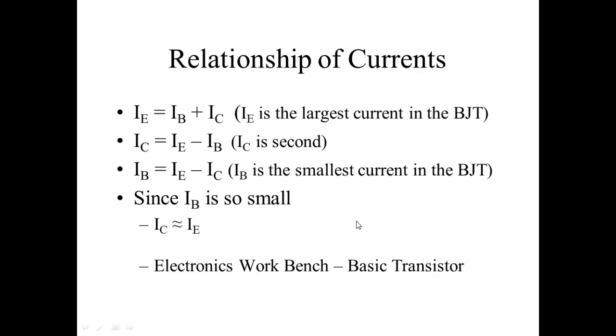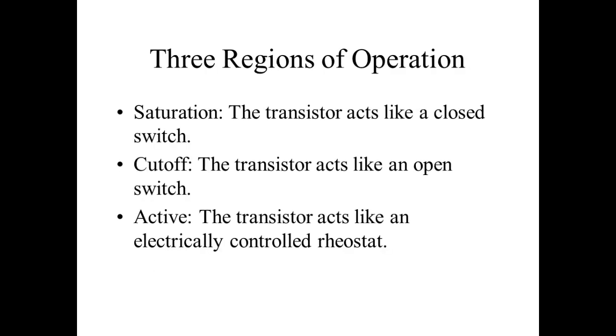What's really cute about Electronics Workbench is we can draw a schematic and it simulates the schematic for us. So these are our three regions. Y'all understand that? Saturation, it acts like a what? Closed switch. It's not a perfect closed switch. It will always drop a voltage. And what's the cutoff? We usually assume if the voltage across the collector and the emitter is less than a volt, we assume that it's saturated. Cutoff, the transistor acts like an open switch.